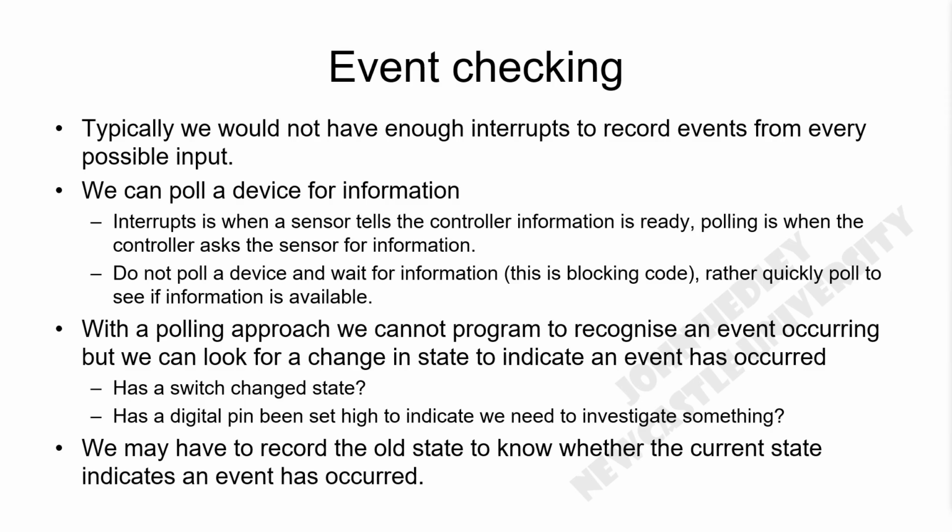If this message was of high importance, namely we needed it as soon as it was available, then we could attach this message available pin as an interrupt. However, we are more likely to just want this information within the next loop of program execution, and so we can have this message available pin as a standard digital input pin that we can poll in our program.